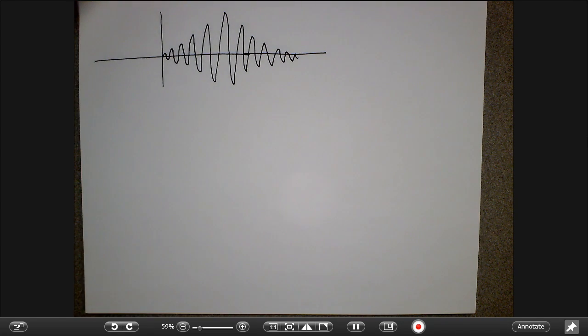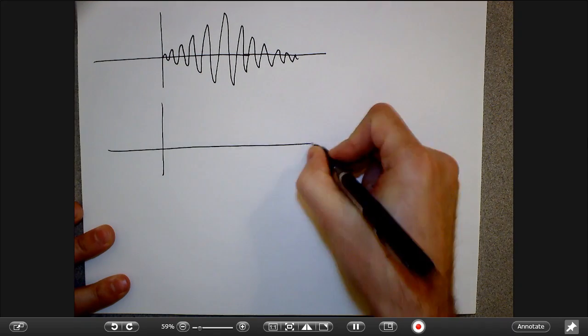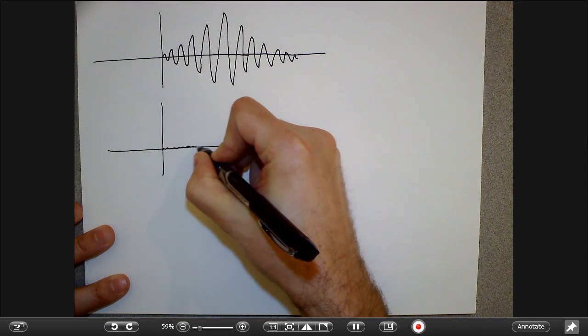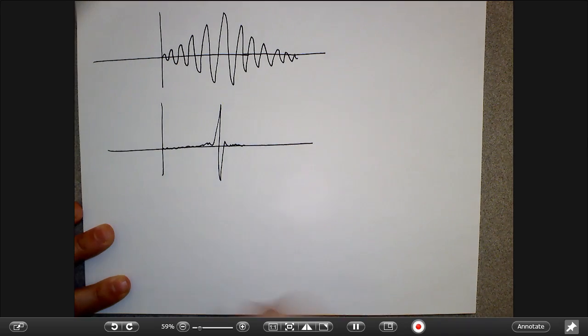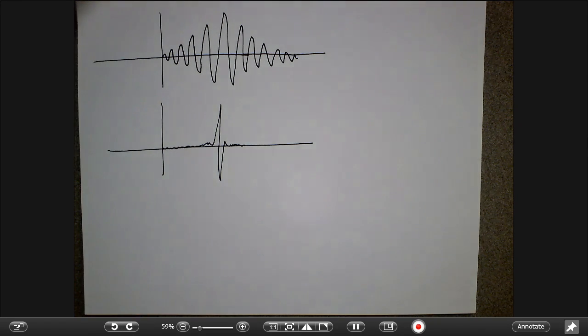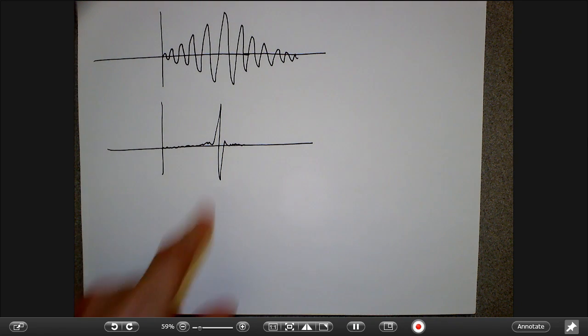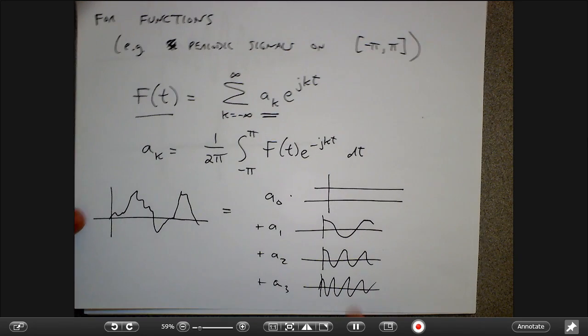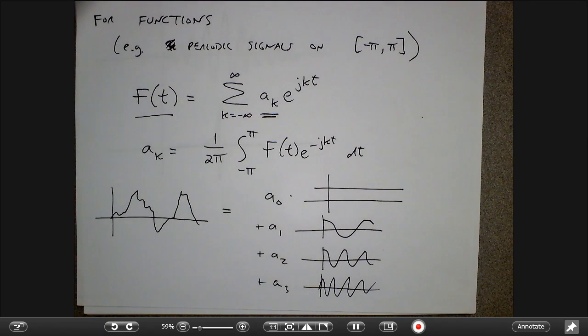So this is like a carrier wave that is modulated by some sort of envelope, right? Even though there's really only fundamentally one frequency inside that signal, a Fourier analysis is definitely going to take more than one coefficient to be able to represent that signal properly, right? Similarly, if I have a signal like this where nothing much is happening, and then I have some sort of a sharp spike and nothing much is happening again, Fourier series and Fourier transforms are awful at representing signals that are really spiky and really discontinuous, right? Because to make up this signal with a Fourier series, I have to make the signal up out of a lot of sine waves that have equal amplitude across the whole band, right? So it's going to take me a ton of Fourier coefficients to represent this signal.